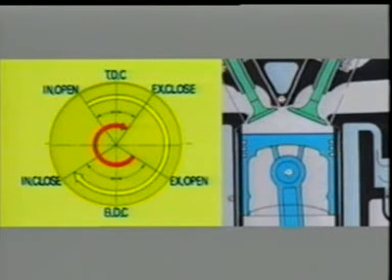The intake valve also opens around TDC of the exhaust stroke. Both valves being open at the same time is referred to as overlap. The mass of the mixture vapors let in at the end of the exhaust process aids in pushing out the exhaust gases still left in the cylinder. The early opening also allows more mixture to be taken into the cylinder.